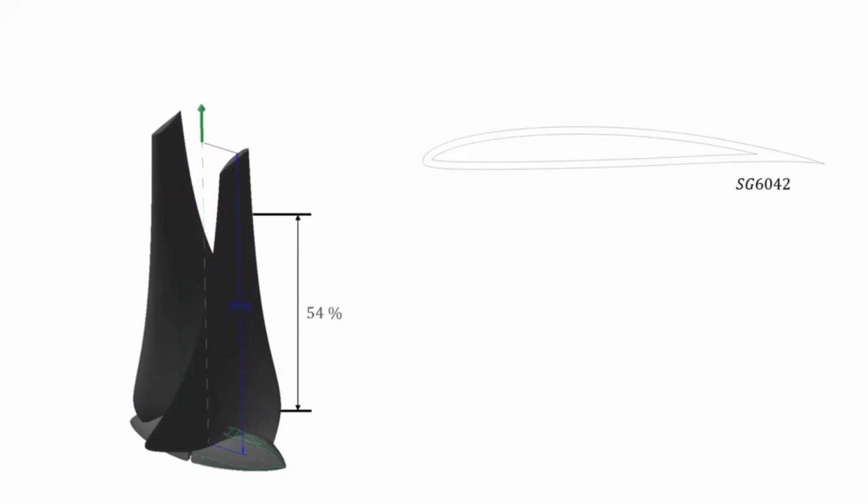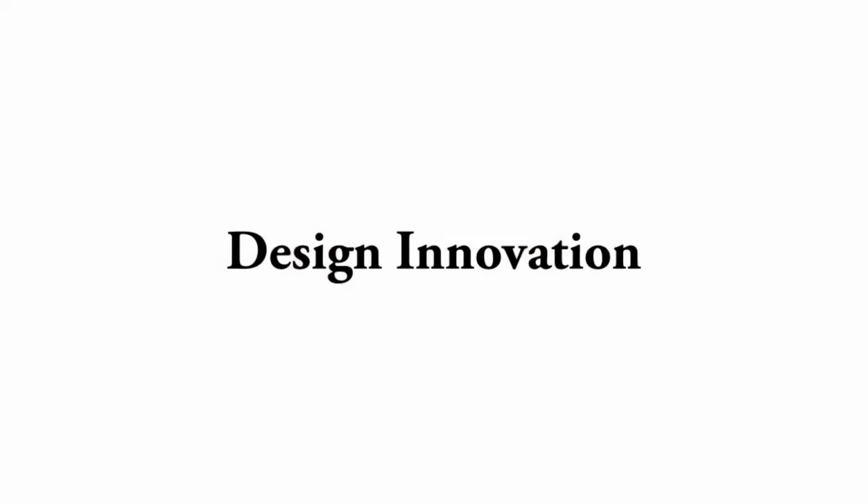Since our minimum viable product requires a mass lower than 200 grams, the blade was hollowed from the root up to 54% of the blade length, with a shell thickness of 1.8 mm. This reduced the total mass by over 28%, while only increasing the deflection by 6.42%.